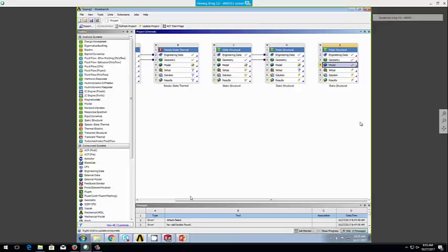Okay, the geometry is apparently there, but you see nothing. So what I need to do is generate some geometry. There's a little button up here in the upper left-hand side. Generate this geometry. And now what we have here is a body. This body is made up of the motor mount. It's a dumb blob of material. Yes, if you look at this, you can sort of see some lines, but it assumes that this body is just one big solid part.